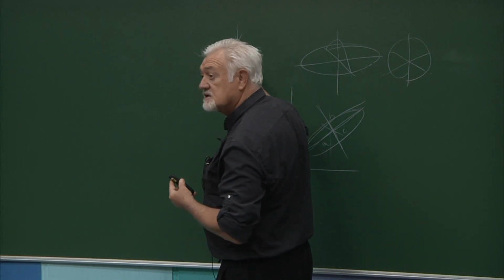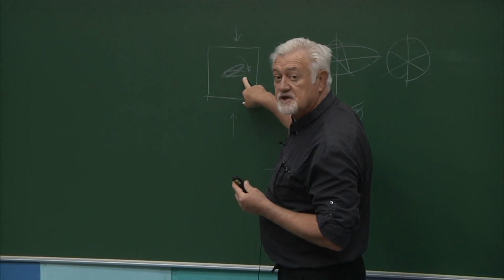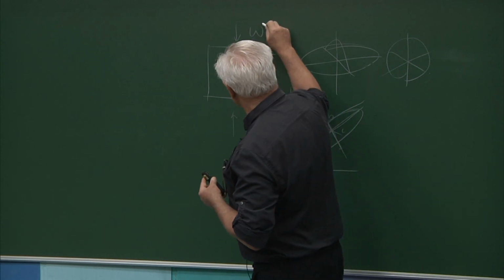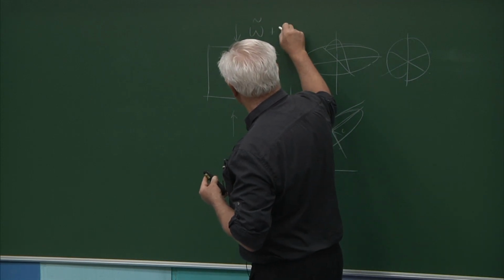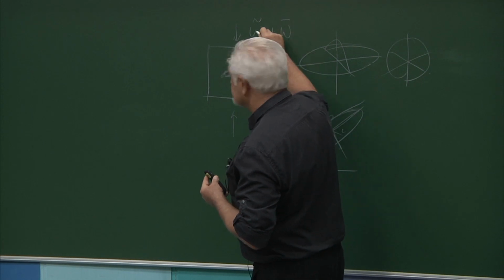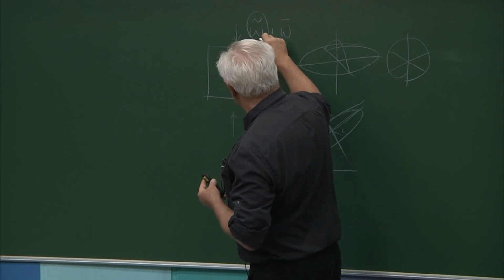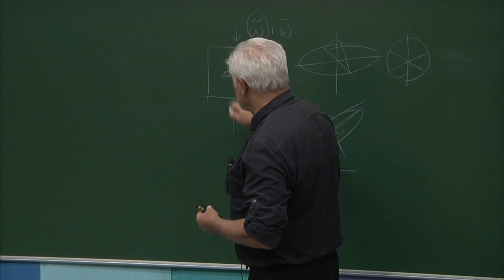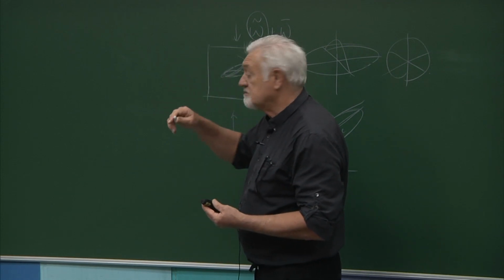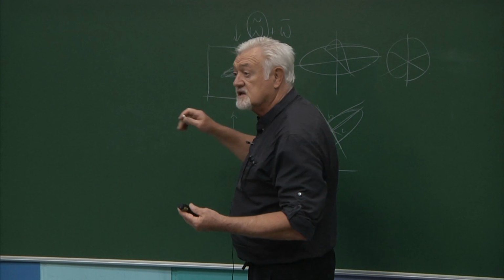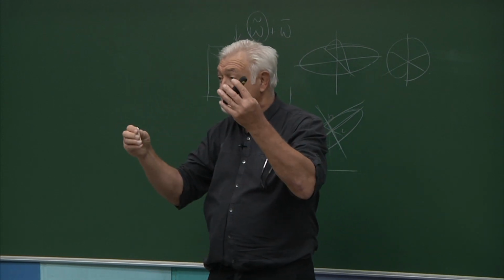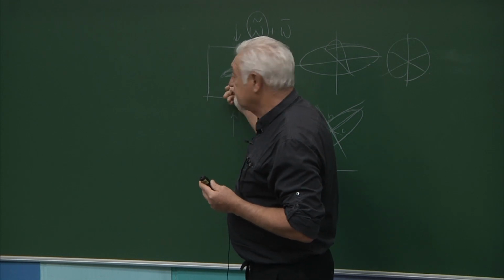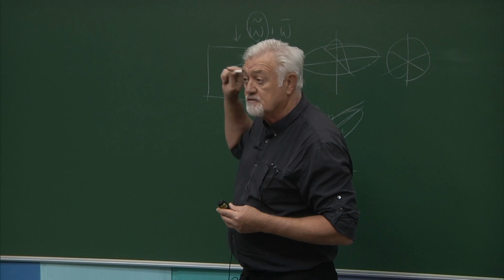So the material around it will tend to rotate this grain around. And that is that term that appeared there, the W tilde. You remember we had a W plus a W tilde. This W tilde is the one contributing to this effect. So you can drag a grain just because of the shape. And of course, if you rotate the shape of the grain, the crystal inside the grain is going to rotate, so the orientation is going to change rapidly in this grain. This effect is captured by the inclusion formalism, for example.